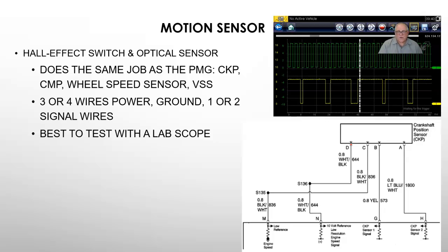I was looking at a Chrysler schematic, and Chrysler said that this was 8 volts. And I was thinking, oh no, I've been lying to people all these years. When we went and tested it, it's battery voltage on the Chrysler. The reason that they said it's 8 volts is because Chrysler uses an 8-volt square wave. Power, ground. All Hall effect and optical sensors have to have a power and a ground. Power, at least 9 volts, a good, clean ground.